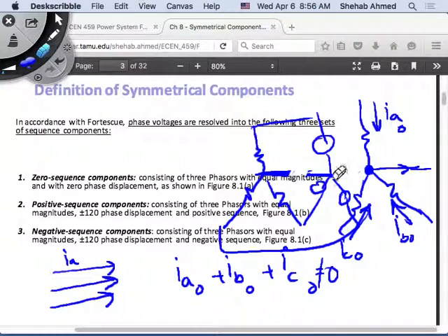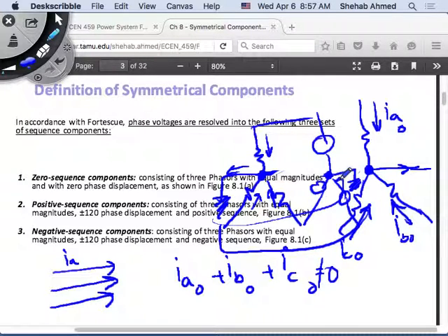and these are far away from each other. So this is a source that is far away from your load. Typically we would have what? Typically we would connect to ground here, connect to ground here. This would put this point and this point at the same potential. So if there is an unbalance, there will be neutral current flowing from your source, through the load, through the neutral, through the ground, back to the neutral of your source, right?